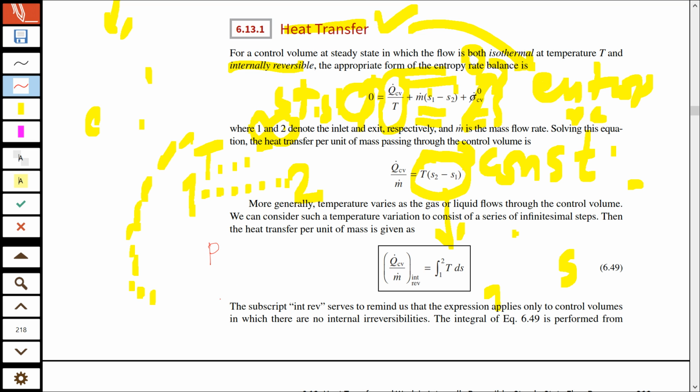For example, if I say that pressure is constant, work done for a compression or expansion process is simply pressure times change in volume. But if that pressure changes over volume, I replace this change with incremental change. Then P varies with V, so it's P of V, and then I integrate between two states. So it's exactly this.